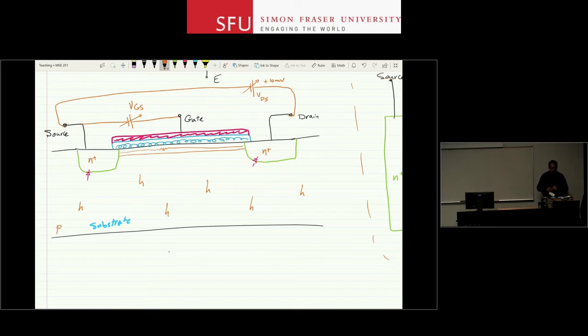The diodes are still there, sorry about that. But now at the very top of that surface, you have an N region, so you go from N plus to N back to N plus. It's the same type of doping. So it's just a resistor at the very top of this, but the rest of the structure remains as before.